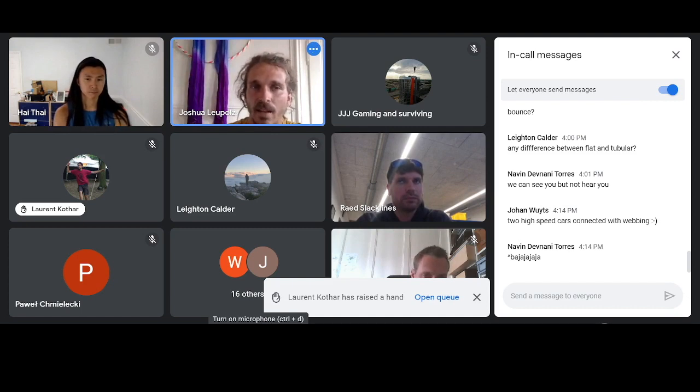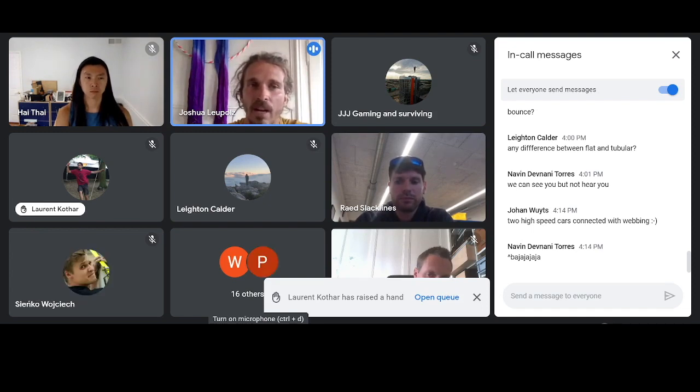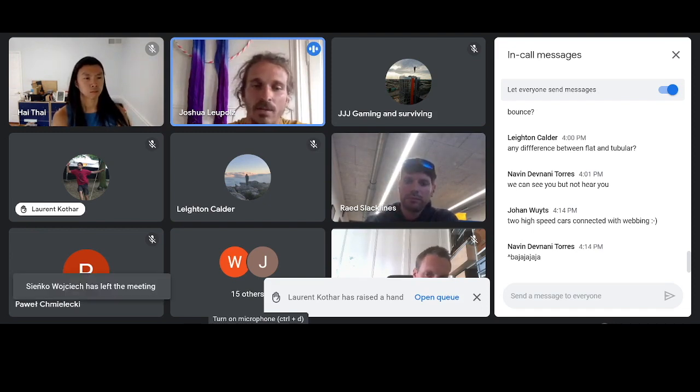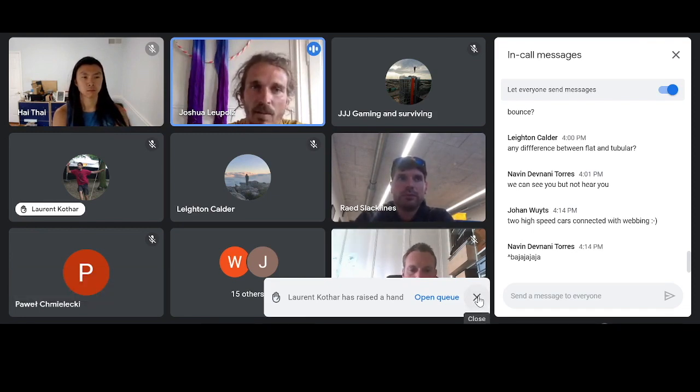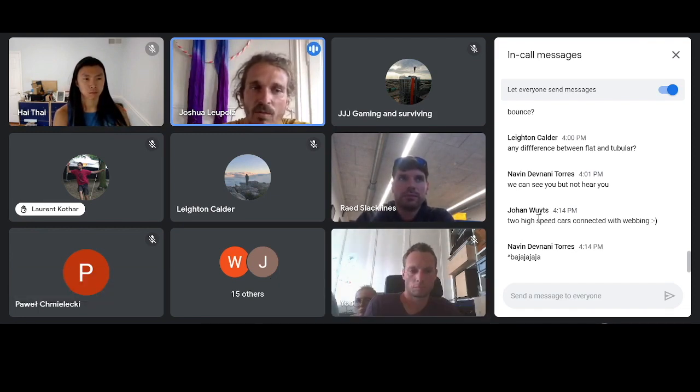And in the end, you just need to hit a few cycles precisely at 5 kilonewton. You do like 20 cycles, and then you search out the cycles which were precisely between 2 and 5 and take the value there. Or otherwise you scale it down. I mean, you don't need to have 3% between 2 and 5 kilonewton. You can also calculate it down and say, okay, if it was between 2 and 5 kilonewton, 3% stretch, it transfers to 1% per kilonewton. And then you are independent of how high you went exactly.